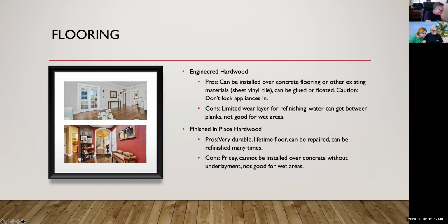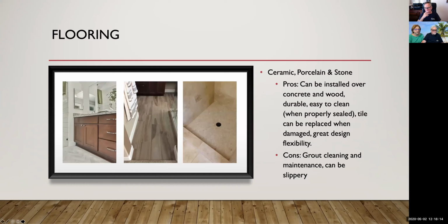Finished in place hardwood, that's the Bentley of flooring. It's very durable. It is a lifetime floor. It can be refinished many, many times. Unfortunately, it's very pricey. Cannot be installed over concrete unless you use a wood underlayment first, and it's not good for wet areas. Oh, flooring, flooring, and more flooring.